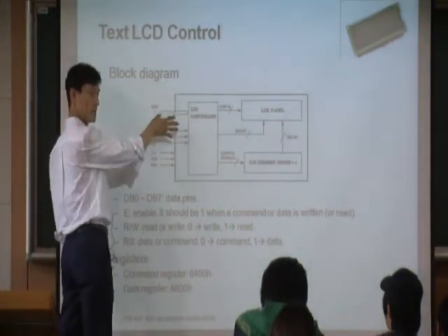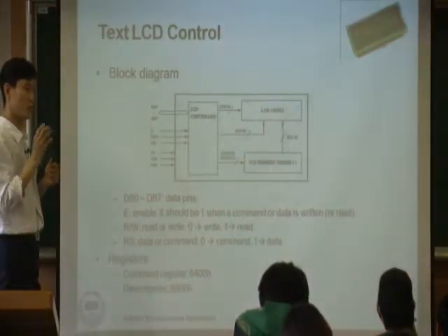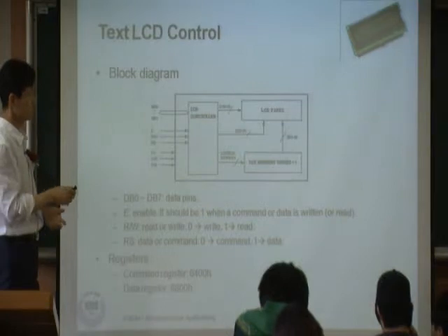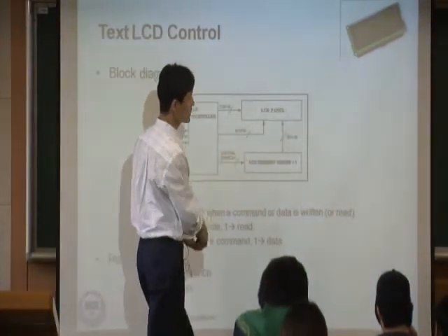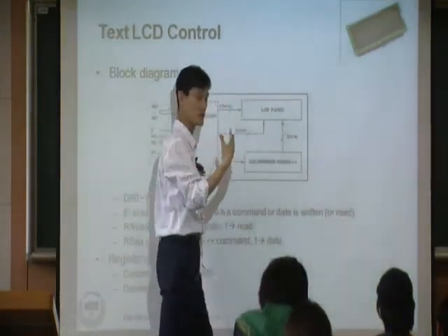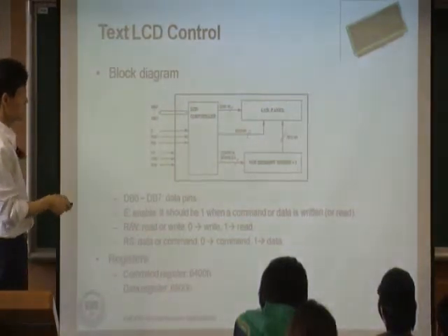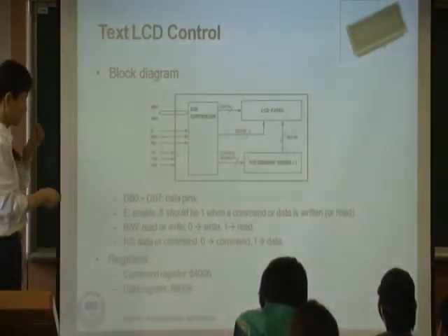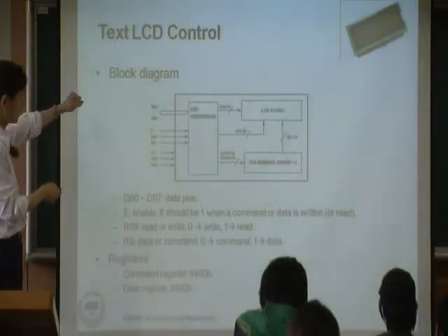Letter A, letter B, things like this. Right? So at only one time, you are getting only one 8-bit. So that's why, in order to display these letters, the whole thing, you actually have to get them one by one, one after another, one after another. Okay? And for this LCD device, you have some control pins, E, RW, read, write, and RS.